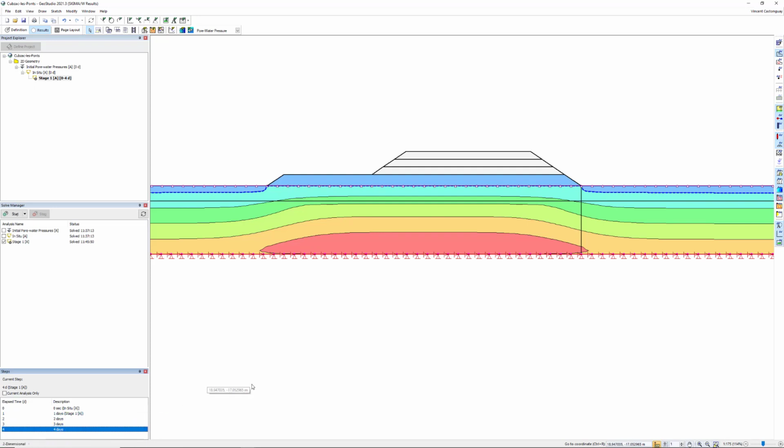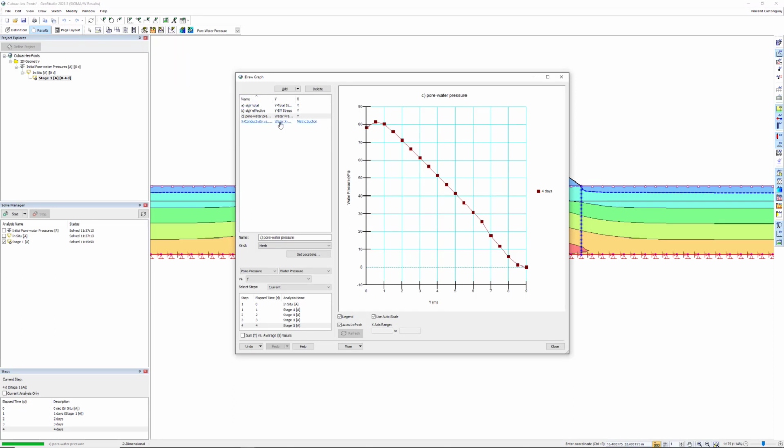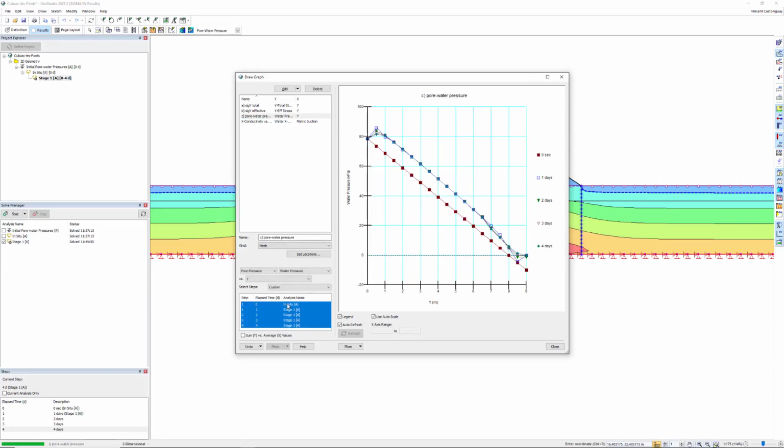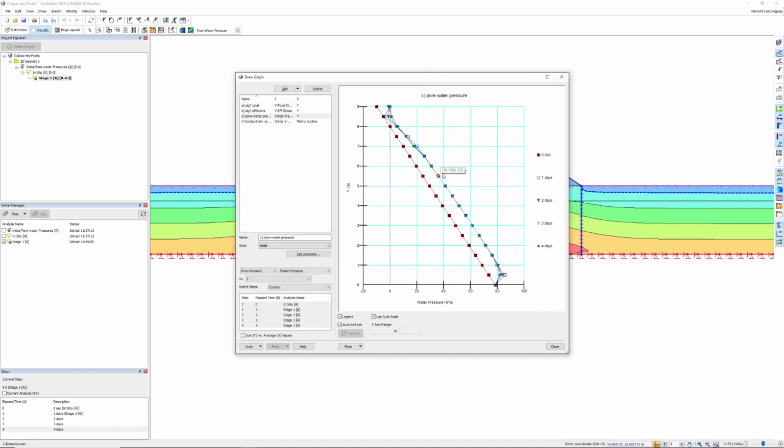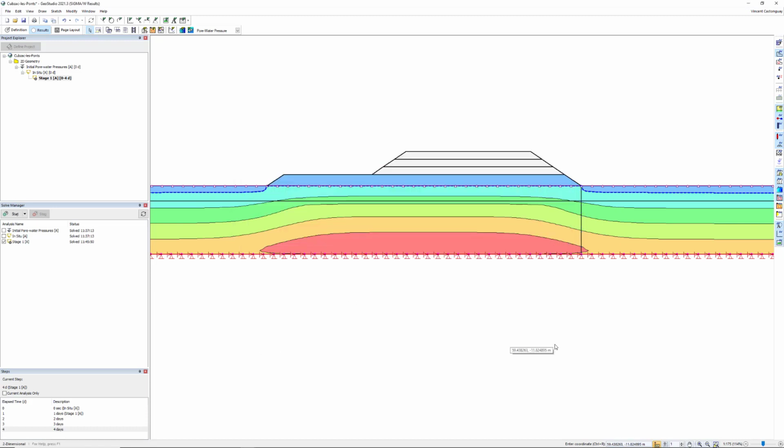Plotting the pore water pressures and multi-selecting all the calculation steps also clearly shows that pore water pressure increased. The red line indicates the starting pore water pressure. If time was allowed to tend toward infinity, the pore water pressure profile would fall back on the red line and these dissipated pore water pressures would translate into consolidation deformations. But instead of allowing the pore water pressure to dissipate further, another lift of embankment will be added on the 5th day of construction.